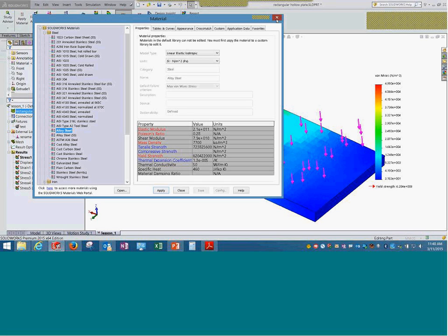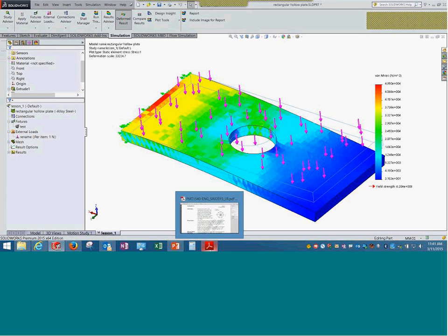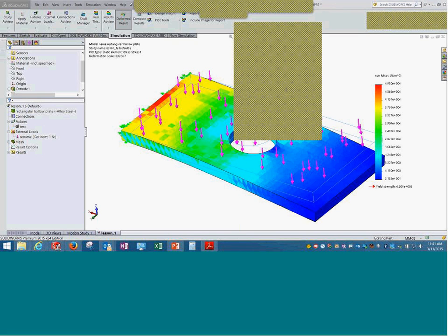I'm looking at situations wherein I'm compressing this geometry in such a way that it has no place to change in the other two directions. Then obviously it has to create stresses and volumetric change. So frankly, if I had to put it in one word, the answer is yes. There will be a certain amount of volumetric change, but it depends on the overall loading conditions.